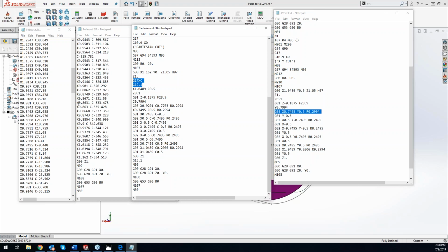And once you have this set up for your machine, because you're going to know if your machine supports it or not, even running a sample part, just like what we have drawn up right here, make sure you save that out as a template. That way, if you're not using this on a day-to-day basis, you can at least have it saved out for your mill turn, for face moves, and it'll already be set up for Cartesian or polar, whatever your machine can support, or just doing the regular XY cut there.